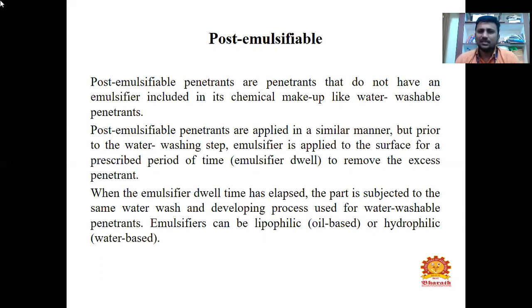The emulsifier is applied to the surface for a prescribed period of time. The emulsifier dwell time, we already discussed, right? What is meant by dwell time? To remove the excess penetrant, when the emulsifier dwell time has elapsed, the part is subjected to the same water wash and developing process used for water washable penetrant.